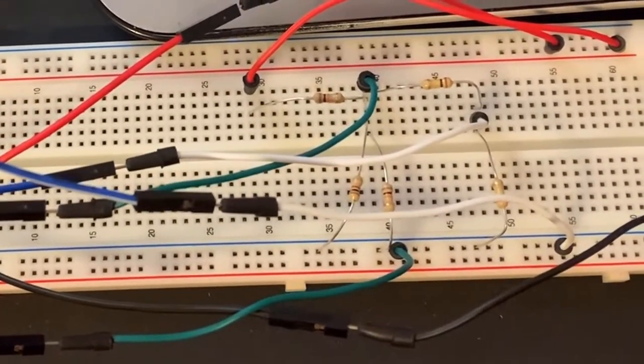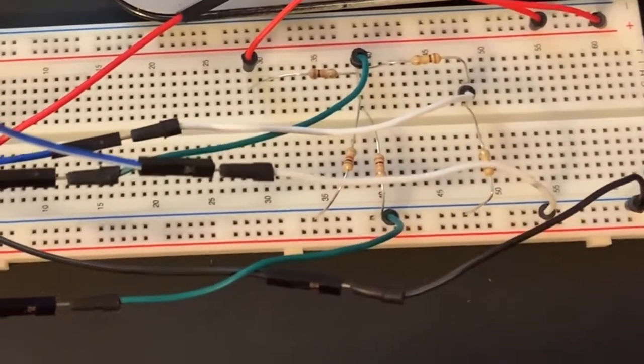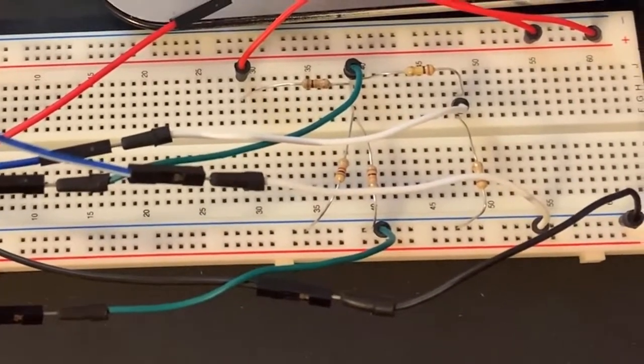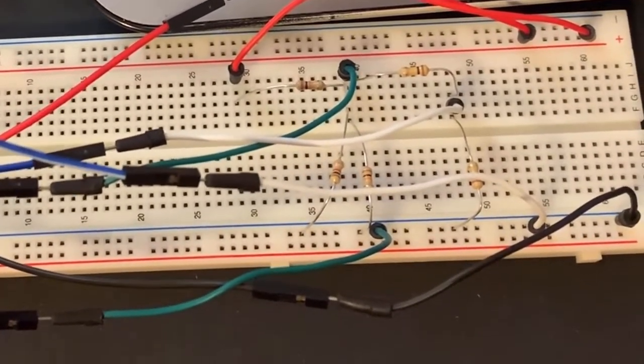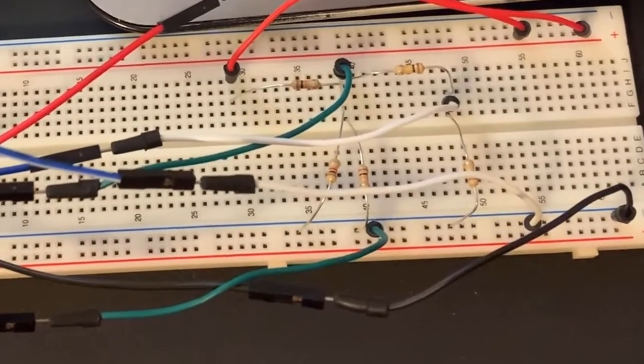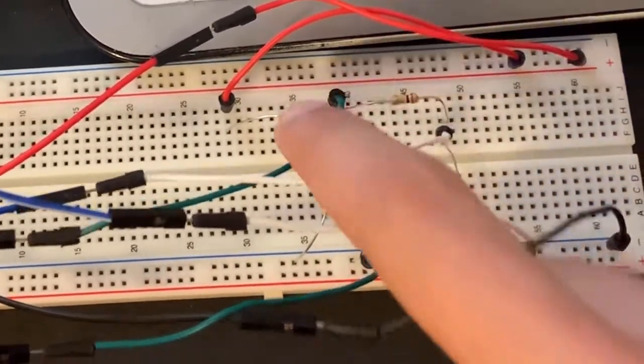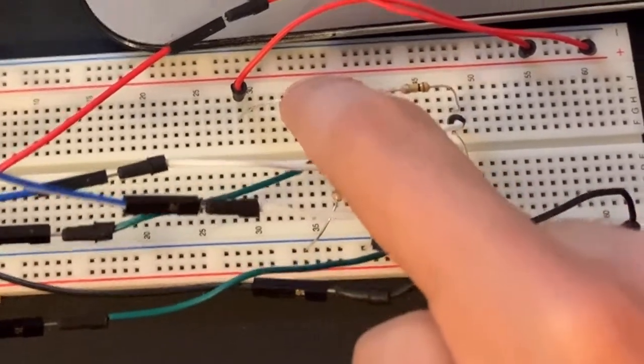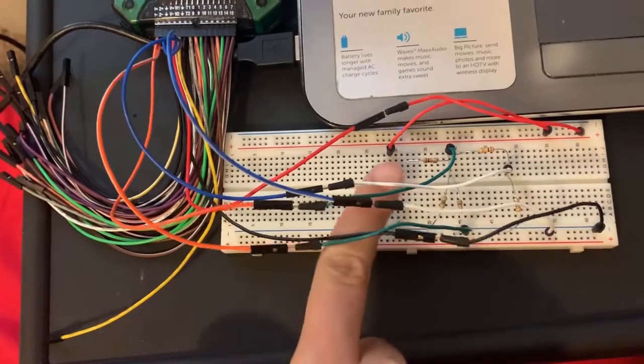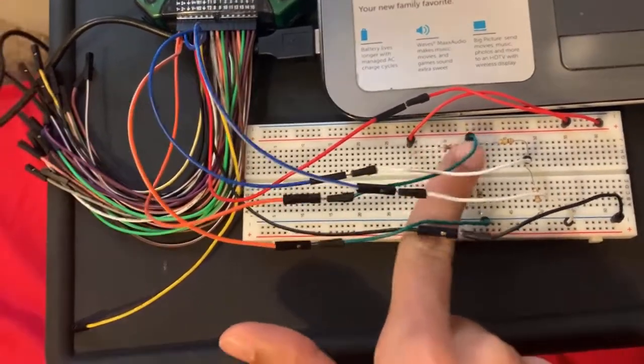Now for part 3, we are going to measure the power dissipation on the resistors. The power is equal to the voltage drop over the resistance times the current flowing through the same resistance. So for example, for R1, the power over R1 is equal to the drop over R1 times the current flowing through R1.